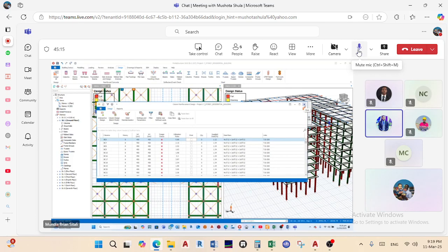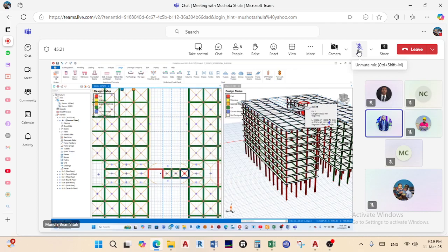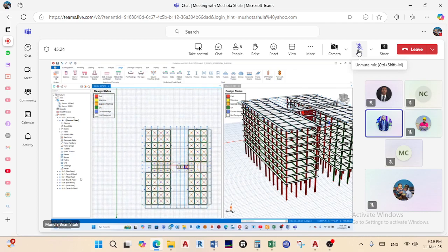So what we do is we'll just close this, and then it's easy to modify them at this point. So when you notice that you're putting in too much reinforcement than is required, you change the cross section. It's the same even with the beams. There are times when you just need to adjust the width of your beam. Maybe it's not giving you sufficient section of the member.